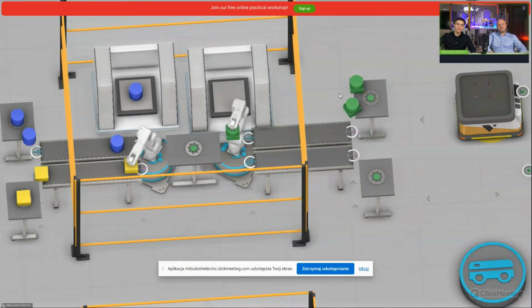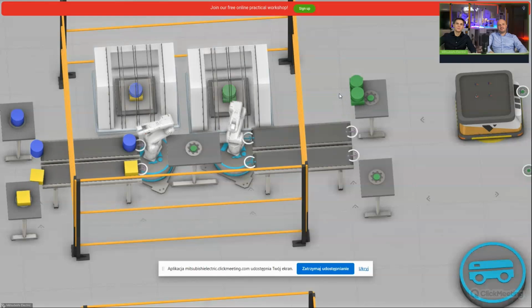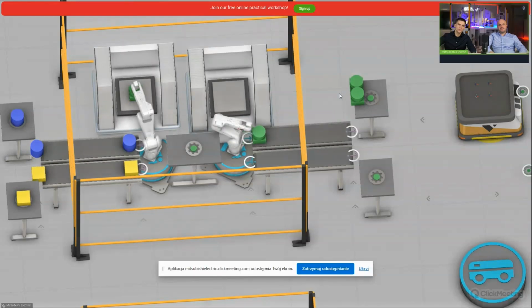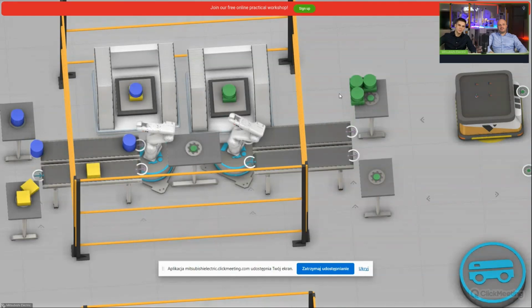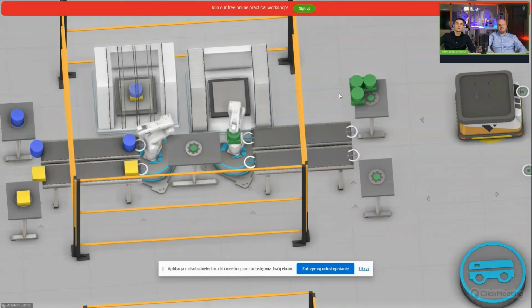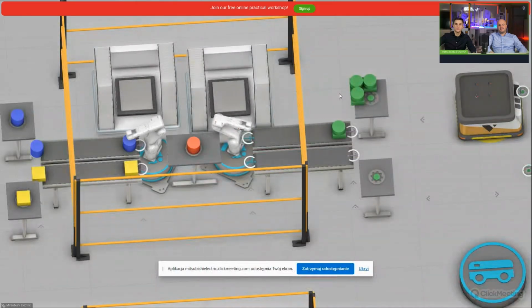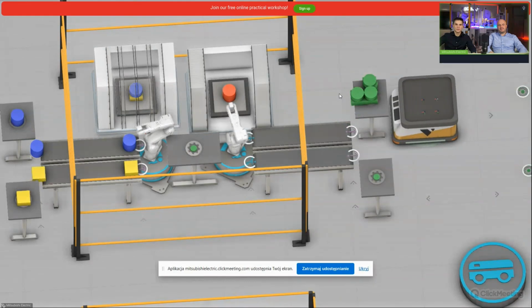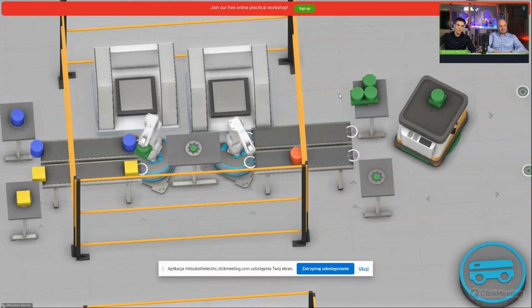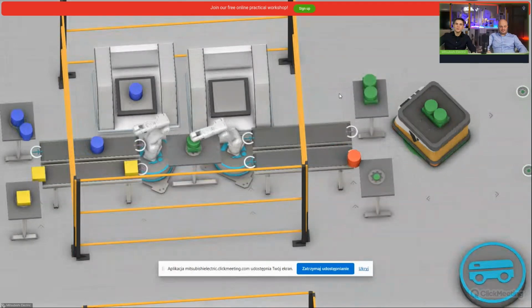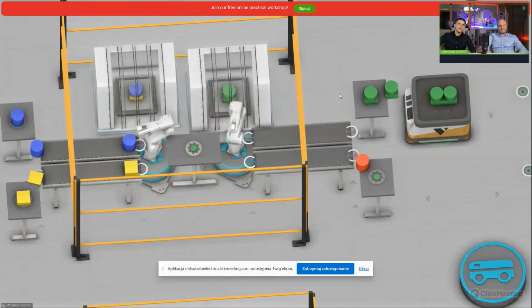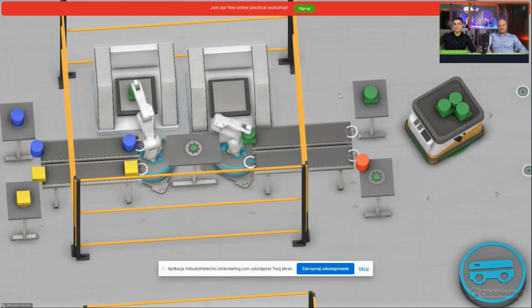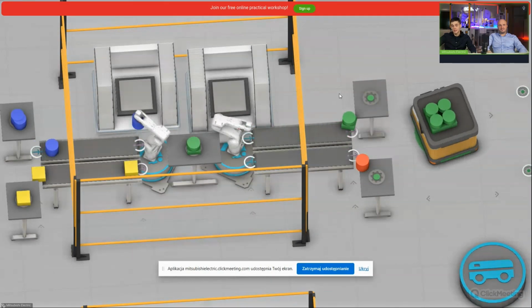When work is finished, the robot passes it to the second robot, and it is inserted into the second machine. Then when work is finished, it is put on the output conveyor. The output conveyor transports it to the storage table. And when the storage table is full, AGVs transport these products to the second part of the line.